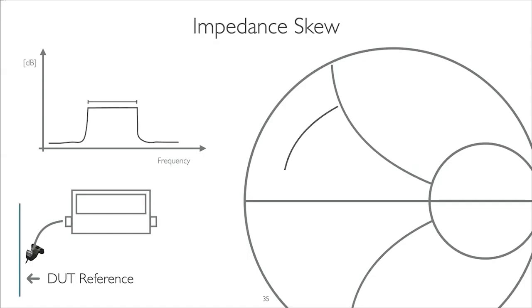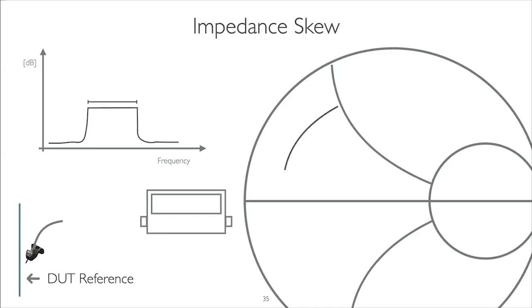But there's also an electrical length component to this. As I increase the electrical length by adding a cable, then this impedance will also be longer. So this is a problem as we get greater bandwidths of signals, and now you're presenting impedances and doing load pull. Now you're not presenting a small, tight impedance. You're presenting a very broadband impedance. And how you interpret that in a measurement system is still to be debated.